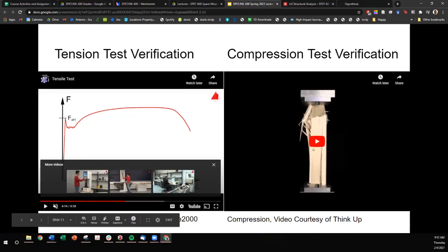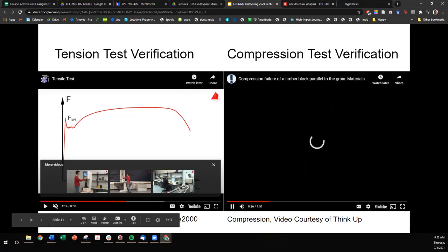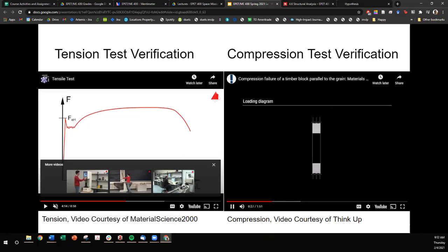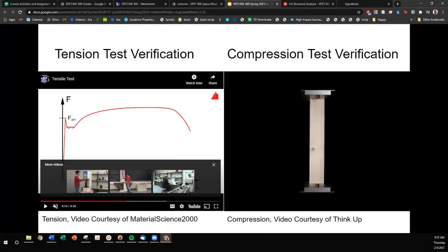Let's look at axial compression loading. Force evenly applied to both ends of the specimen. Compressing forces are now being applied to the specimen. When wood is stressed in compression parallel to grain, each wood fiber acts as an individual hollow column with some support from the neighboring fibers.